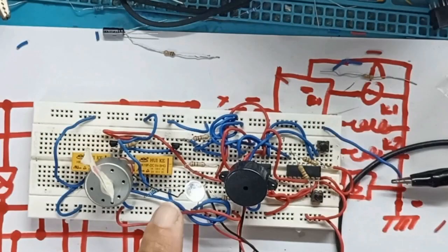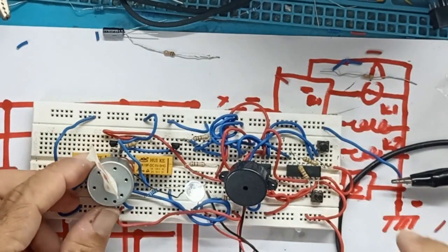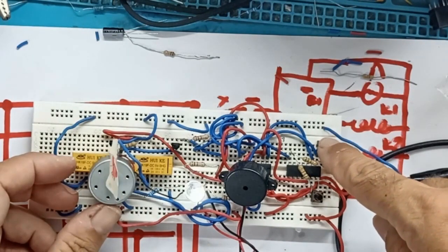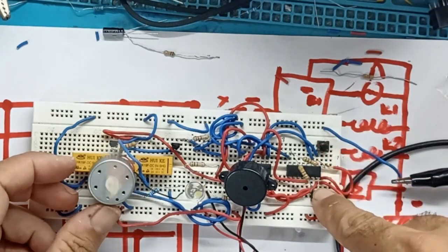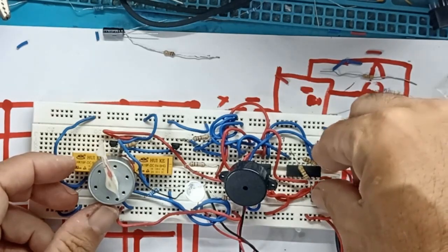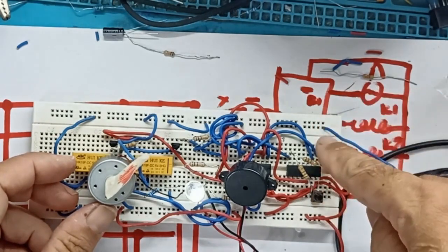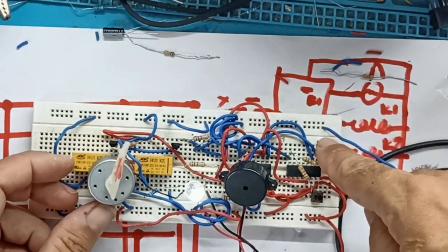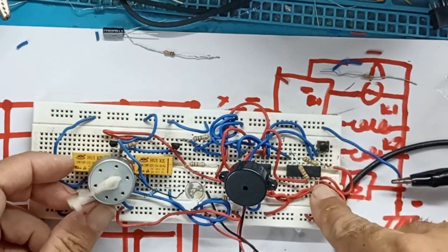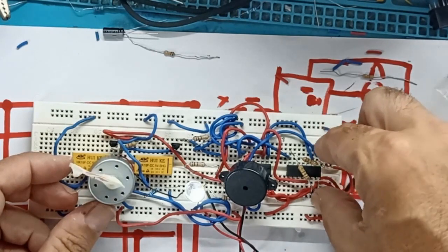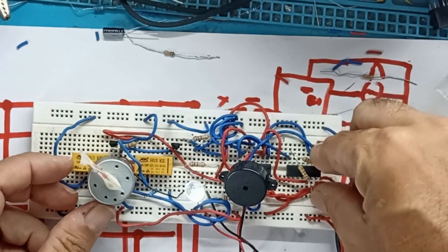Well, let's go for a test. I have connected 3-phase power. We see that the indicator light turns on, showing operation. We press the first button. The indicator light turns off. The motor turns to the right. Press the second button. The light goes off. The motor turns left. Press both. The light goes off again, and the buzzer works. So our circuit works correctly, as we designed it, as we made the truth table, as we made the functions, as we finally implemented it. It's great. With all the combinations, no matter what we do to it, it will do what we have designed it to do.